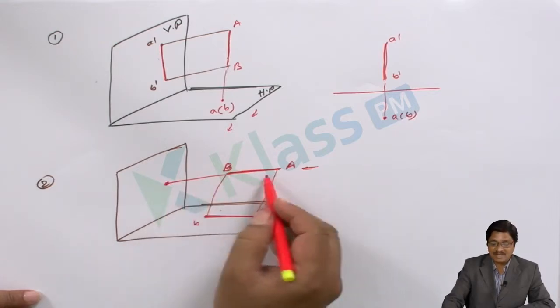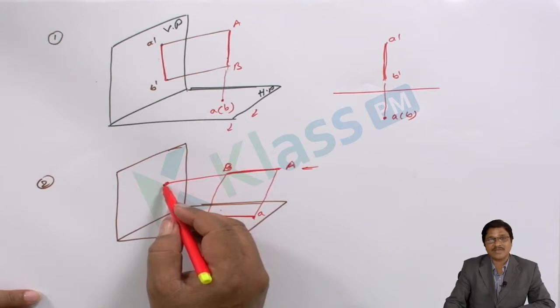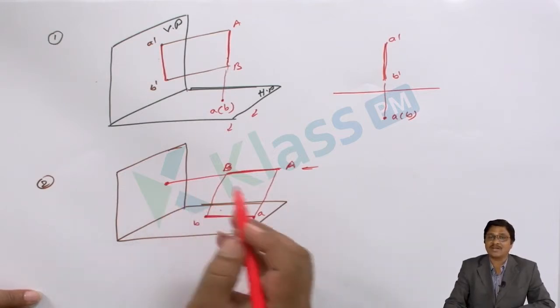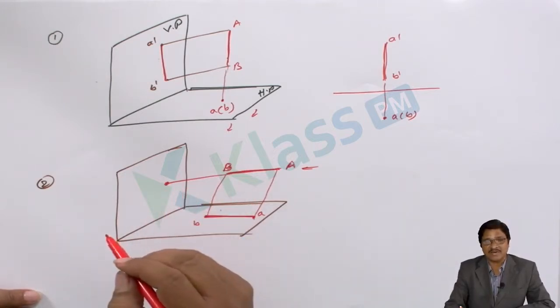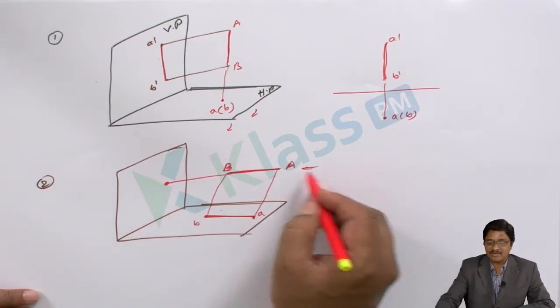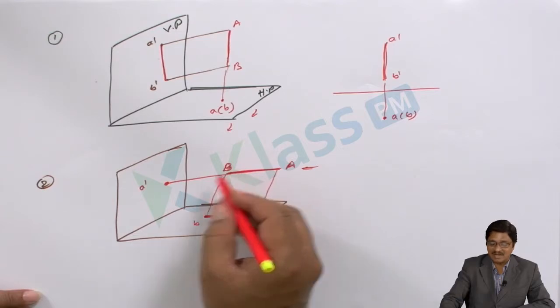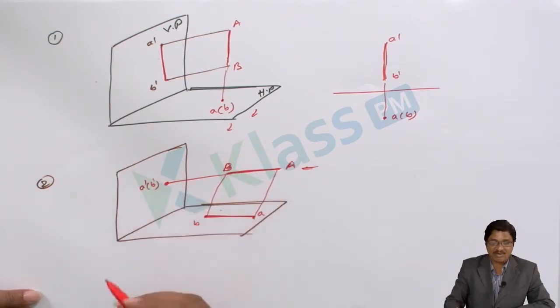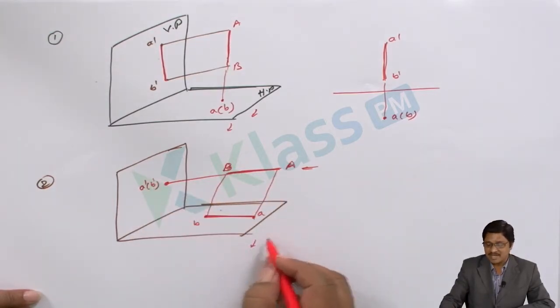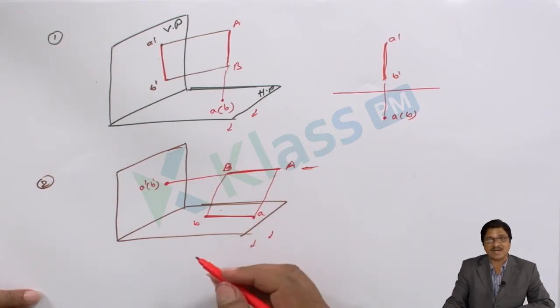Since it is a line but it appears as a point, you have to differentiate how the point relates to the line. So there are two points to be identified. While identifying, the one that is visible when you are viewing should be mentioned openly, and the one exactly behind, which is not visible, should be mentioned in brackets. Once this is completed, it has to be rotated 90 degrees in the clockwise direction.